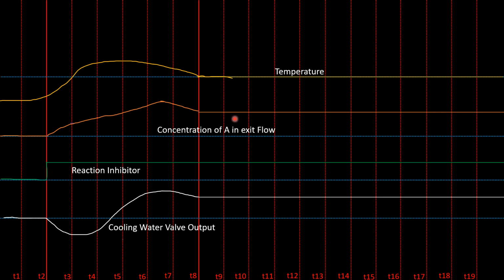So this shows the importance of why you need an override controller and how there are always going to be trade-offs. If an abnormal condition occurs, then we've got to protect the equipment over protecting costs or whatever the normal operating control variable is being used to control. Safety will always supersede quality, as we can see with this example.